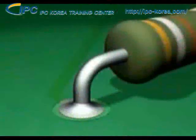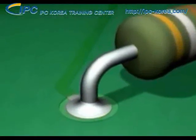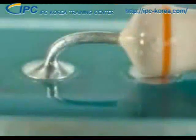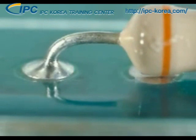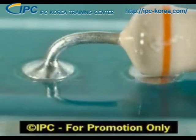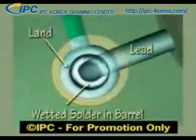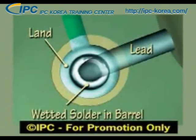Let's start by looking at the component side. The first parameter we'll examine is land coverage. The target solder connection will have a properly wetted fillet that covers 100% of the land and feathers out to a thin edge over the land area. It is allowable to have 0% land coverage on the component side as long as all other minimum solder coverage requirements are met on the barrel and solder side of the connection.